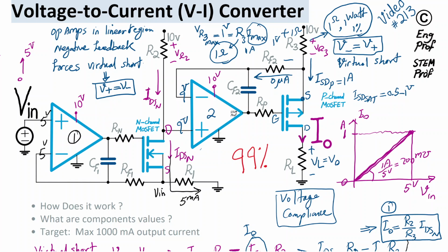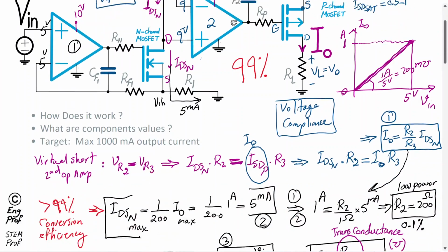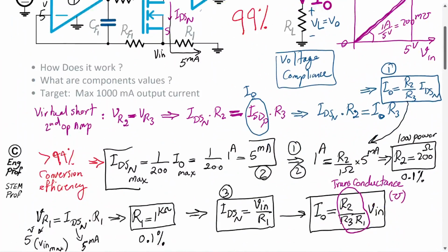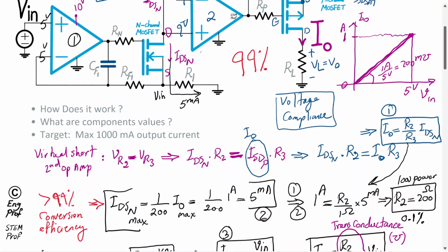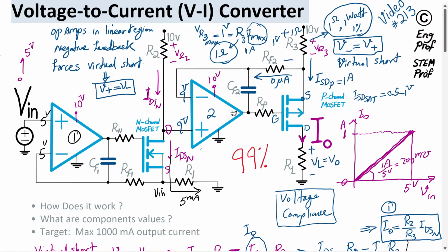So you don't need to go after high current op amps. The only thing that is important about these op amps is that they are recommended to be, let's say, CMOS op amps, so that input current is very small, with very low offset or zero offset, and also very low drift, so that over temperature and over time, the value of offset at the input of the op amp is going to be minimal. That way, we guarantee the stability of the circuit and accuracy of the operation.